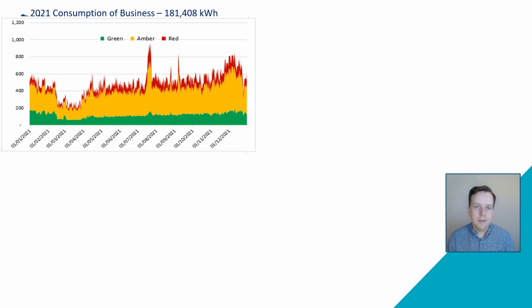So in terms of energy efficiency, you'd be looking at, well, what is this? Because the golf club would be closed between midnight and 7 a.m. What is this base load of electricity use? It is in fact fridges, compressors, IT, security, any number of systems.